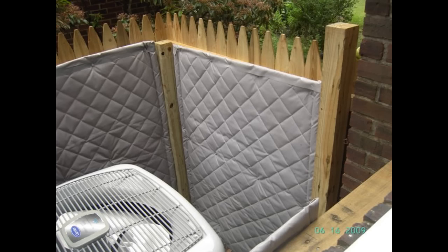Most of the big air conditioning chiller situations that I was involved in, they preferred to have 4 foot around all the units, but they normally would allow us 3 foot for the air circulation and the big fans that come up out of the top for the cooling without affecting the warranty of the operation.